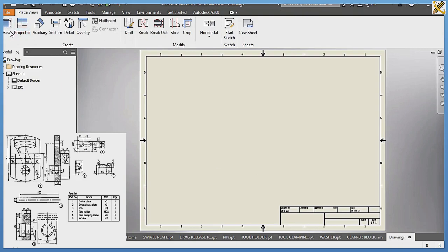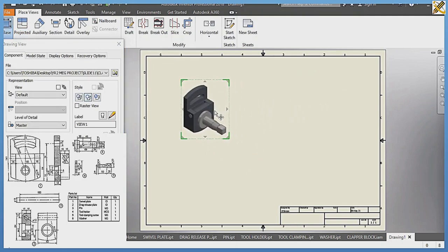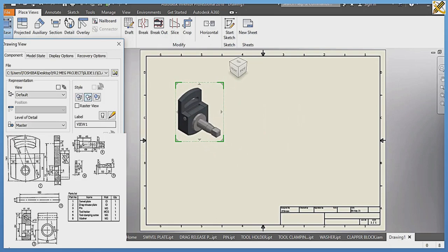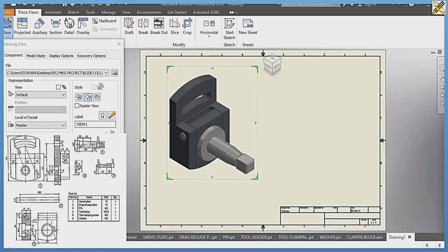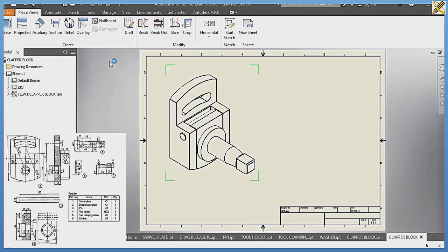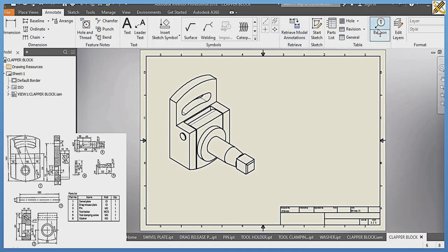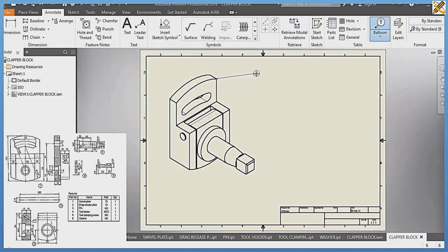Okay, so base, picking the base, it gives me my isometric view. Let me increase the scale, something like 1:1. Let's see how it looks. Better, yeah, see. Then press okay. Alright, so picking my annotate, balloon. Starting from here, as mark 1.